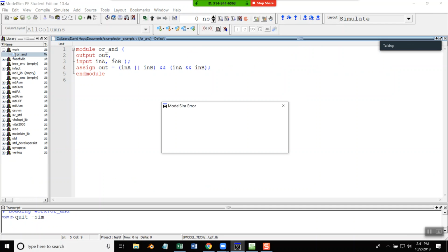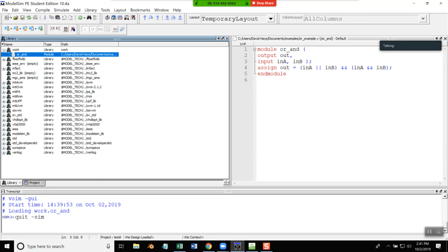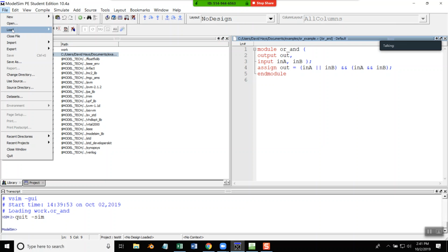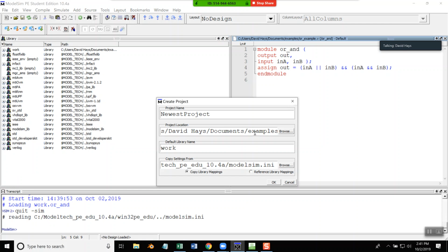Now when it pops up with this, you want to do create new file. Give it some kind of name. And I think we're choosing Verilog, although you can do other languages as you see. Then click OK. Now when that's done, you click this X to close this window. If you double click testing.v here, it opens it up. Now here's where you write your program.